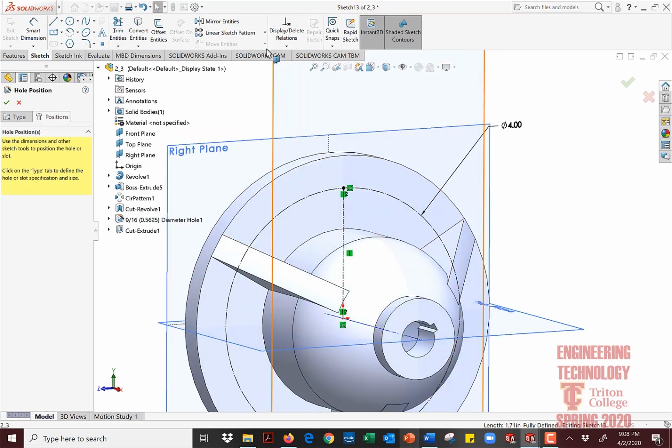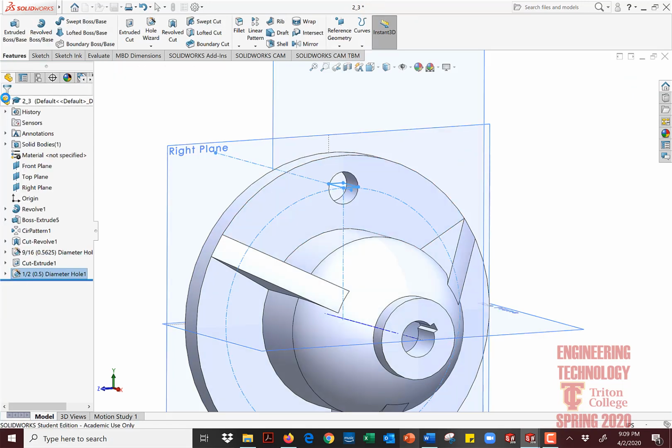I want that because then my last step will be to actually use point. Point is what Solidworks uses to define the center of where my hole will be. See how wherever I move my mouse, my little hole is moving with me. So when I click that, perfect position. That's exactly where my hole will end up. Dead on. No questions, nothing. And that's it. I'm done. I hit OK. That hole is exactly where you need it to be.